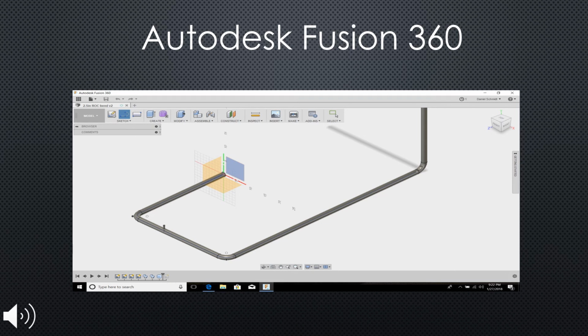The first step in simulations was the construction of a geometry of the physical model. We used Fusion 360 to make a simpler version of the model, and because we're only concerned about the flow physics in the riser, the geometry does not need to include the pumps and sensors. Later we simply input the different injection velocities as boundary conditions and declared the edges of the pipe as no flow boundaries.